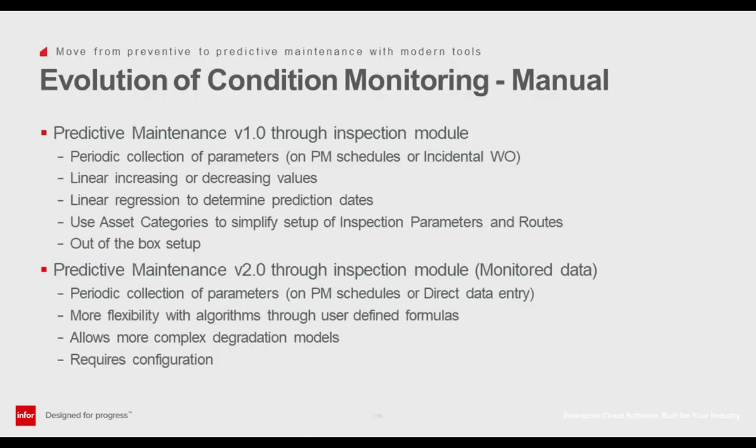Basic ones that you have in condition monitoring have an evolution as well. If you think about the evolution of a condition monitoring event, a long time ago we would set up the periodic collection of data. So I would go out on a work order and write in the notes, here's what I found in the oil analysis. There may be some filings of metal that show an image of gears grinding, as an example. I could see where the bearings have been packed with oil too many times, or lubed too many times. The Zerk fittings are coming off. There are different types of issues that go on that are visual.